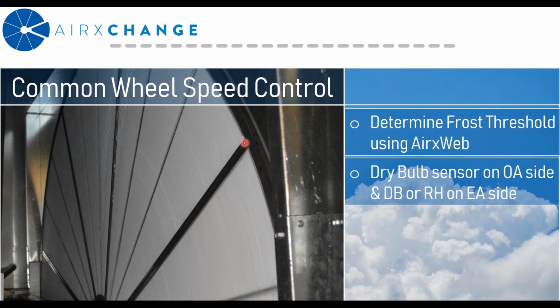So in both systems, you'd use the dry bulb sensor to monitor whether the outside air temperature is below the frosting threshold. And you would use the subsequent sensor on the exhaust air side to modulate the damper to achieve a desired either leaving air temperature or relative humidity.